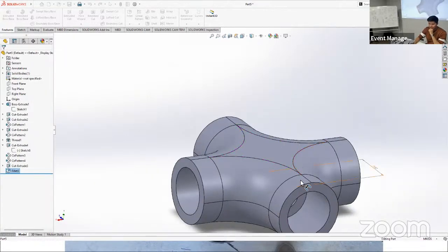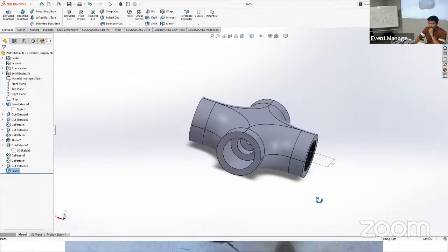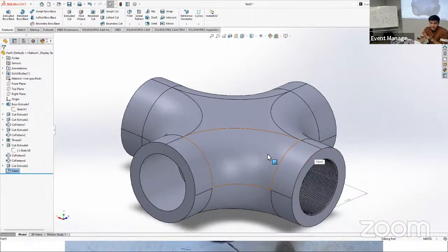So that's our finer, more beautiful way to do it. The first one was the simple connector from a block of metal. It is easy to manufacture with the simple instruments that you have, but the fillet that we did makes it more complex to manufacture, because for doing those complex shapes, you need a 3-axis CNC machine, which is like a robot that costs a lot of money. And if you do not have that access, you may not do that. It also increases the cost of manufacturing.